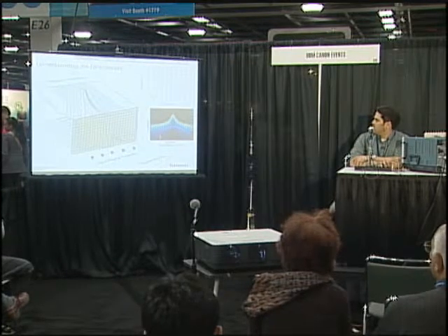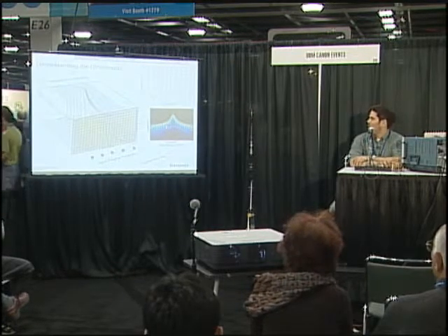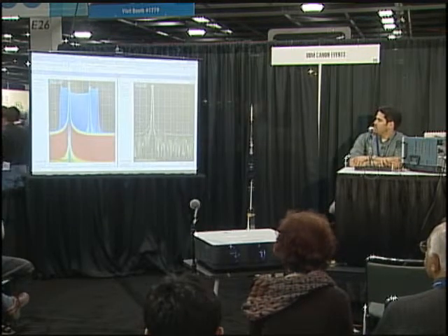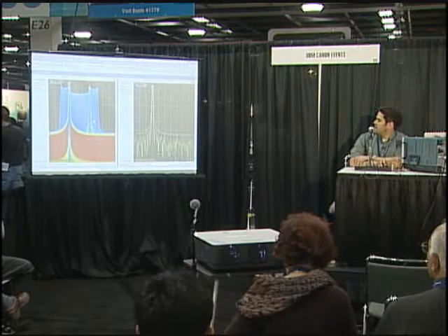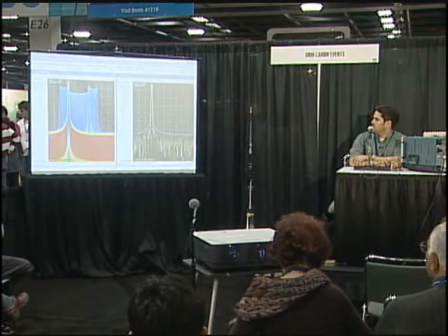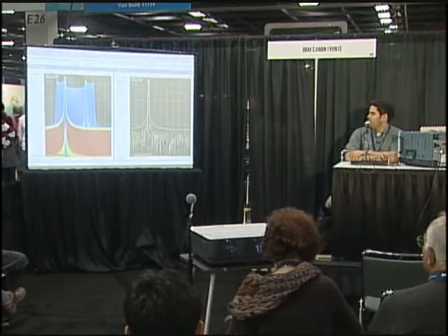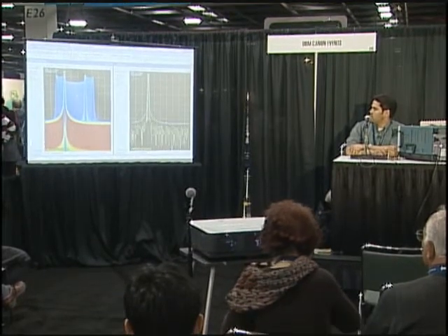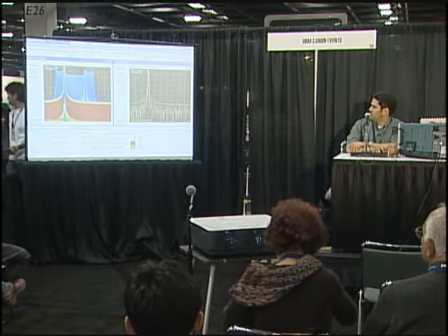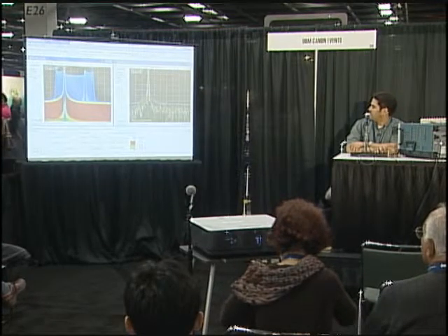And then if we go high resolution, it looks like this. And that's exactly what we were getting on the previous display. So take a look. This still hasn't seen the transient, and this is catching every single time. And what it's telling me is based on these colors, and there's a scale, by the way, that tells you, red means very frequent, dark blue very infrequent, and so on.